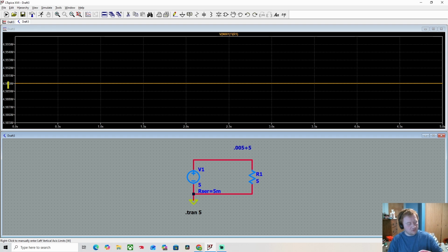That 19 volts will be used for a bunch of downstream processes so that you can get your exact voltages, but you're going to lose something with every component that you add. You're going to add stress to the system, so that 19 volts can only be regulated or kept at 19 volts up to a certain level. And that all depends on what each little component draws. Everything adds up together in their various combinations of series, parallel, whatever you have. That's why power supplies have a current rating in general.